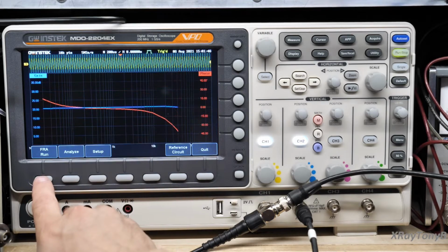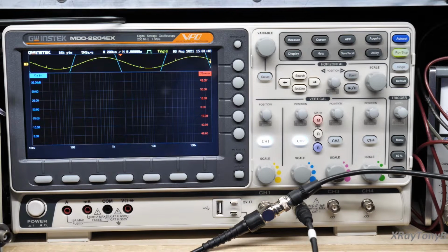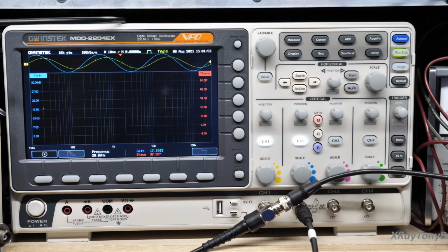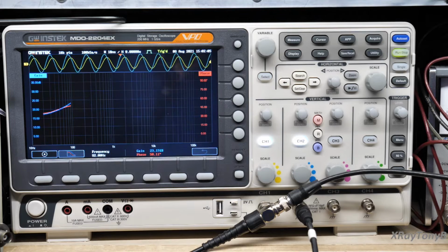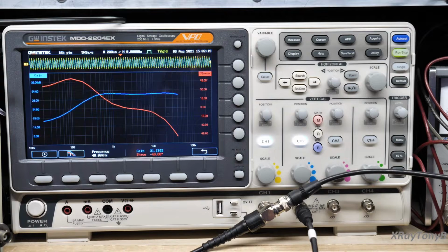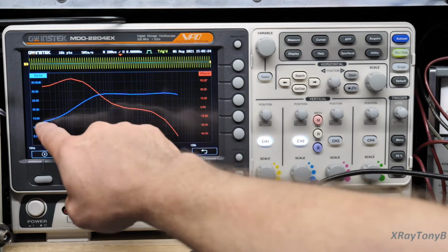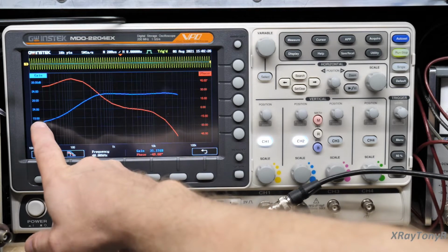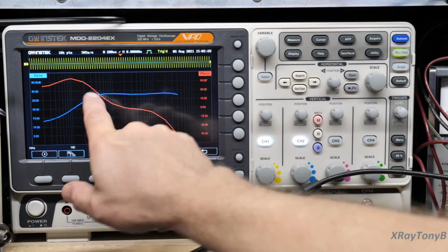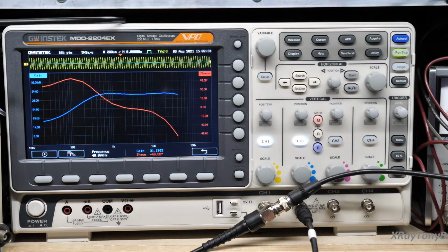Let's run our frequency once again. I have the bass control turned all the way down now. And look at the blue line now, what happens. See what happened? Because I have the bass control down, notice the gain of the amplifier is lower at the bass notes, but it becomes flat at the mid-range and treble. And that's what you would expect.